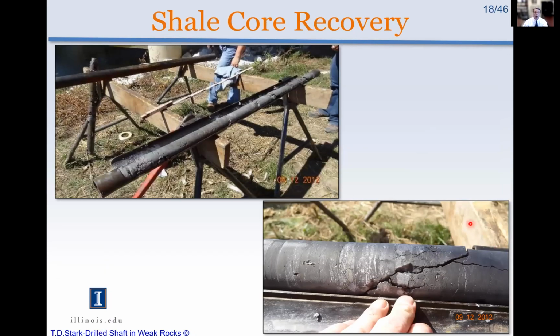Here's the core. So typical core barrel, 2-inch, about maybe 1.5 inch diameter. And that enabled us to cut the triaxial specimens right from the core, test it, and measure unconfined compression test, or UU triaxial, because we were also interested in Young's modulus. So here you can see some of the core.